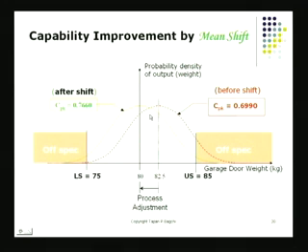The other way to try to improve a process that has got poor capability is to shift the mean. If the mean was off target, you adjust your factors in such a way that the average of the process shifts and becomes coincident with what we call the target of the process, which has been set by doing some market research. It turns out you'll have a larger area of your process that will come within the tolerance limits,